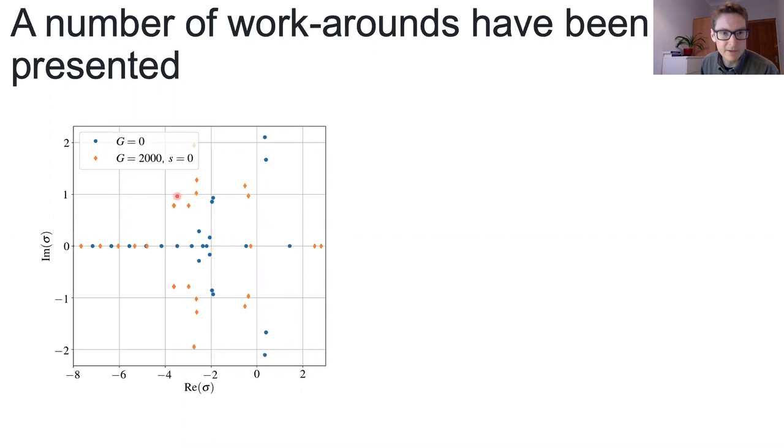If you just naively employ a time delayed feedback control method to try to stabilize this solution, you can stabilize the complex eigenvalues. These two come across the imaginary axis and are stabilized, but the one which is purely real is actually amplified. So you make this eigenvalue more unstable, and this exemplifies in some way the odd number limitation.